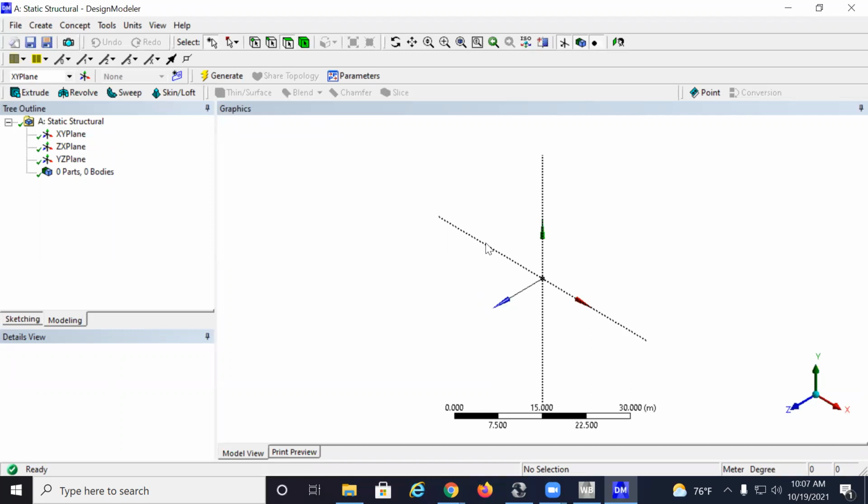And from your CAD experience, creating a solid part, we can use extrude, we can use revolve, we can use a sweep, we can use a thin loft. So what we're going to do here for the part, we can create it either using revolve or extrude. We're going to simply extrude 2 sections to create the part that we analyzed before. In order for the part to be oriented along the x-axis, I want to start with a section defined in the YZ plane and then extrude it in the x direction.